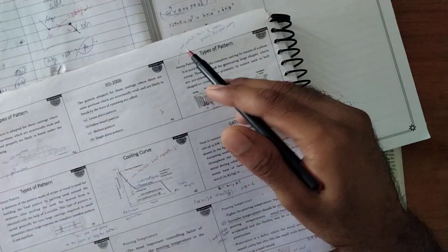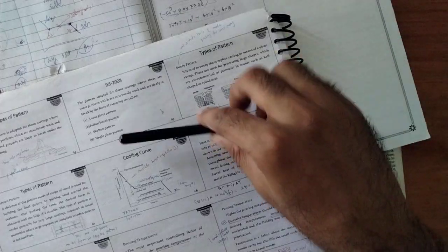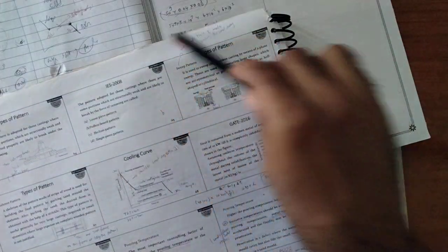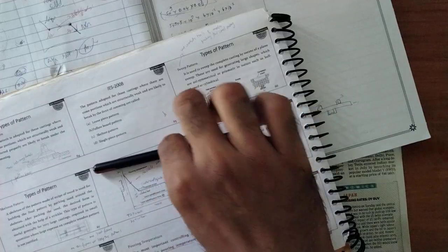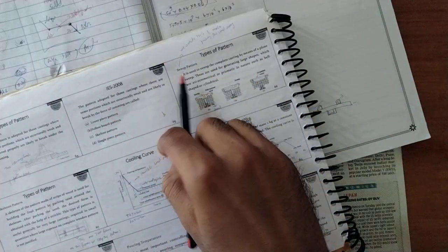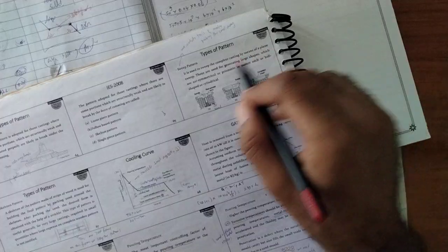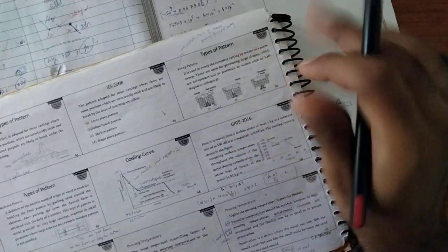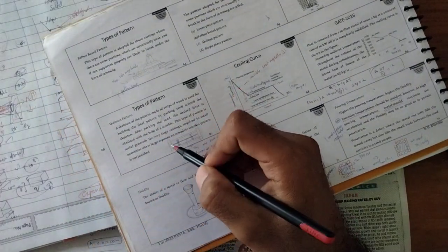Okay. Sweep pattern means we just sweep. For example, if I need a round shape, I just keep my pen here and rotate it, and directly I get a round. So it is used to make complex castings by generating a larger area, axis symmetrical and prismatic in nature. That's it. Skeleton pattern is a smaller thing, because here you can see a little bit of empty spaces. This is a skeleton pattern.